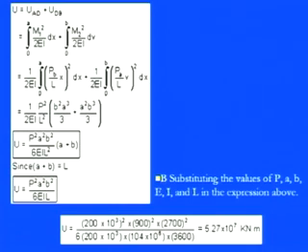Now using the moment equation for the strain energy, UAD is replaced by the integral from 0 to A of M1 square divided by 2EI dx, and UDB is replaced by the integral from 0 to B of M2 square divided by 2EI dx. Now we need to replace that part. Taking out 1 by 2EI, we have the integral from 0 to A of PB by L, because M1 is nothing but PB by L into x, whole square into dx, plus 1 by 2EI taken out.